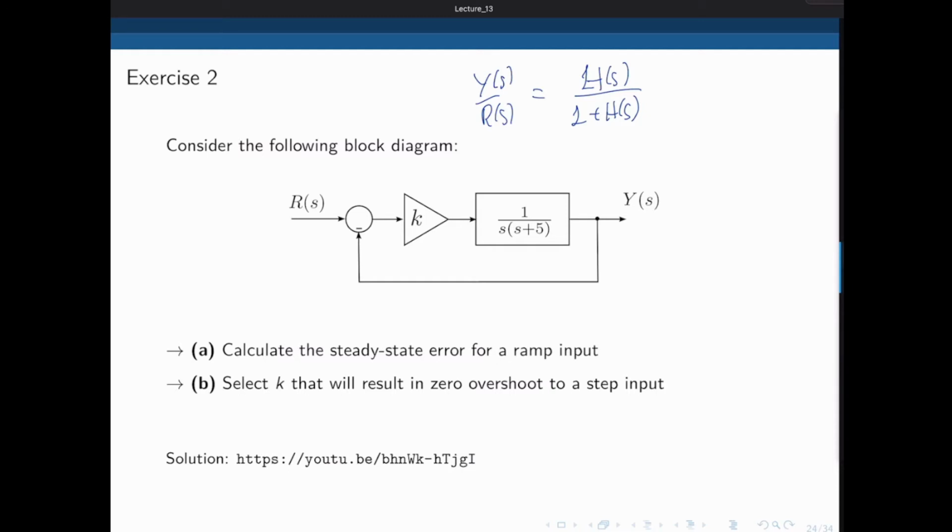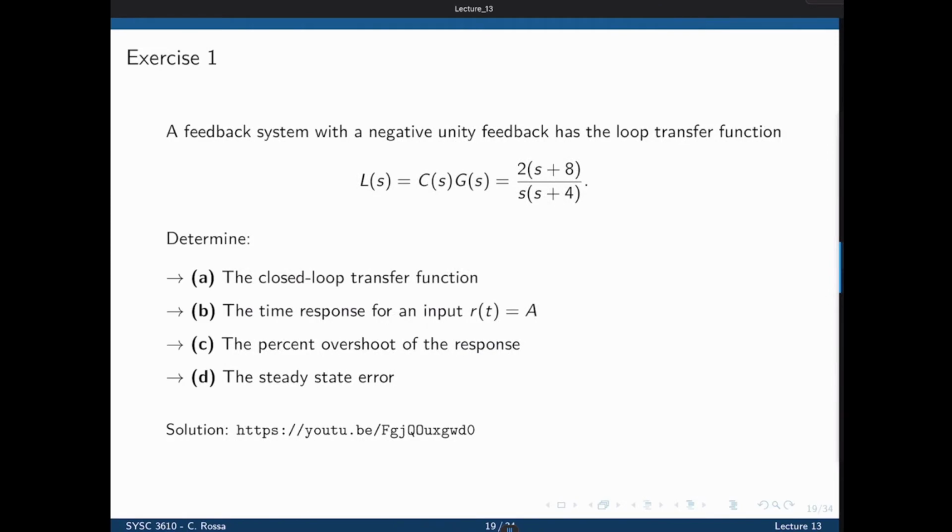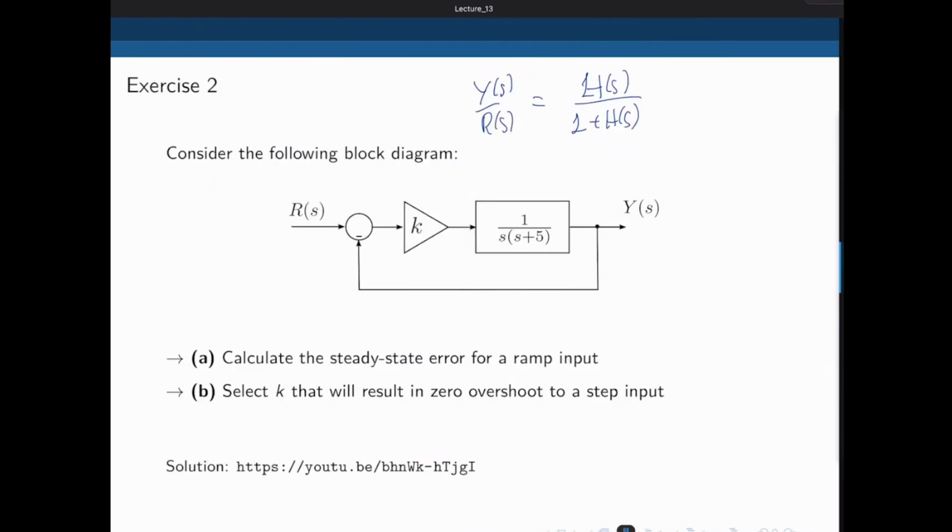Professor, during this time, may I ask a question? Sure, go ahead. Just want to clarify: when the poles are closer to the imaginary axis, the system is going to be faster. Then is the settling time longer or shorter? The settling time is taking longer, but the system will first cross the final value faster, and then it will take some time to settle.